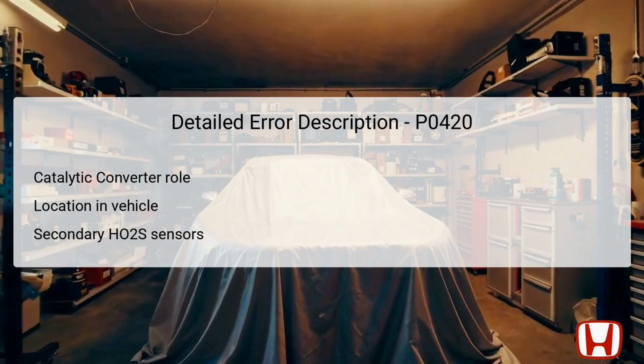The secondary HO2S, which is used to monitor the efficiency of this conversion process, measures the oxygen levels in the exhaust after it passes through the catalytic converter. When the PCM detects that the fluctuation integration value of the HO2S exceeds a specified limit for a certain duration, it assumes that there is an issue with the catalytic converter's efficiency, leading to the storage of DTC P0420. This could mean that either the converter itself is failing, or there are problems upstream affecting its performance.